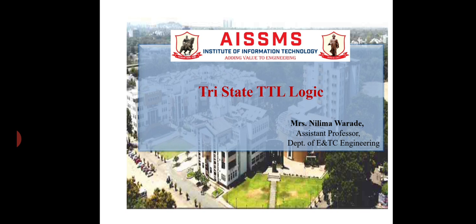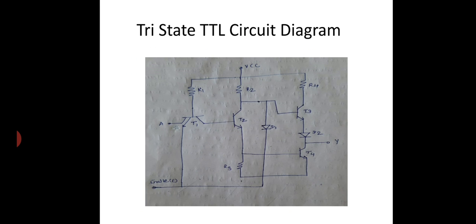Today, I will be discussing Tri-State TTL logic. Tri-state or three states logic means the logic allows an output port to assume a high impedance state, effectively removing the output from the circuit, in addition to the logic 0 and logic 1 levels.